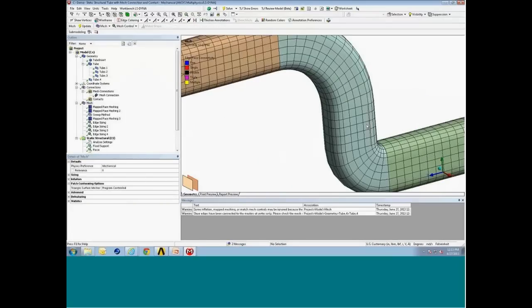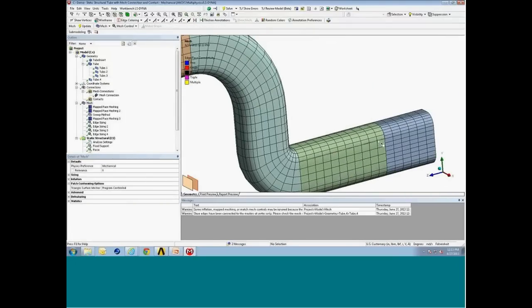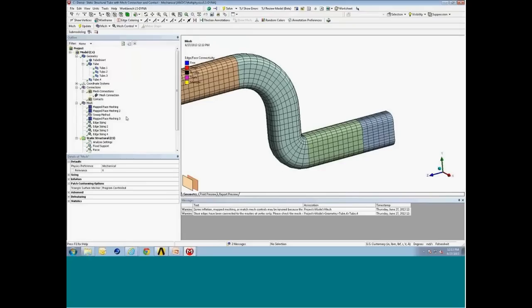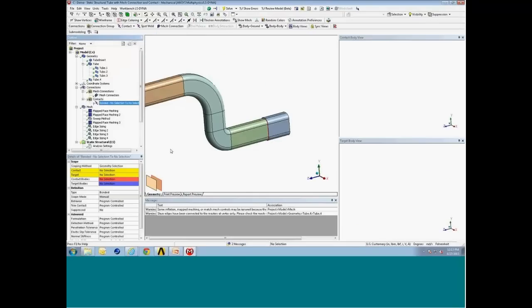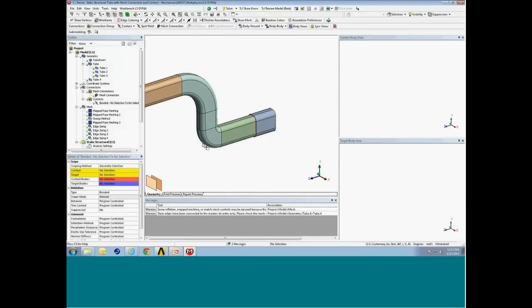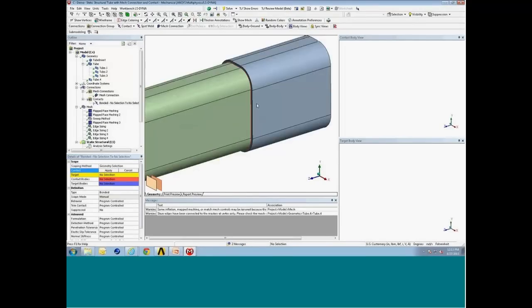And you'll see that we can confirm that the outer profile of the solid is consistent to that. Next connection I'd like to demonstrate here is the use of contact between different types of geometries, surface bodies and solid bodies. So in our contacts folder, we can insert a standard bonded contact. And with the bonded contact, we're going to set up a specific MPC-based contact. With this MPC-based contact, the contact side has to be the surface body.